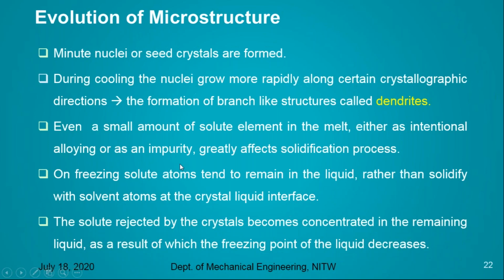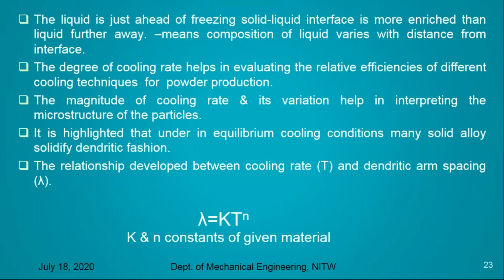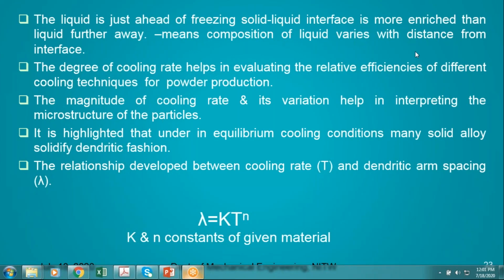The solute rejected by the crystal becomes concentrated in the remaining liquid as a result of freezing. The melting point of the liquid decreases in the liquid just ahead of freezing. The solid-liquid interface is more enriched than the liquid further away, so the composition of the liquid varies with the distance from the interface.